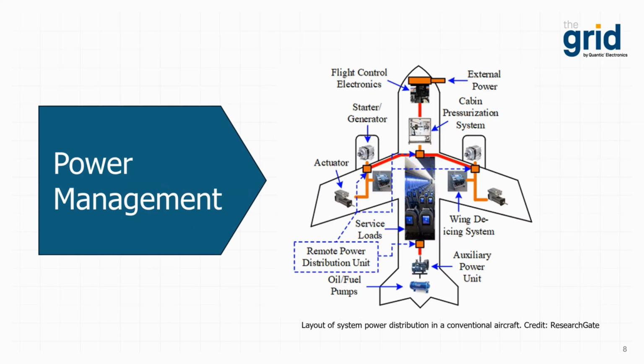Capacitors help maintain stable power supply voltage by decoupling and filtering out high-frequency noise. This is crucial for sensitive avionics equipment. Capacitors store energy to help critical electrical systems continue to have power during brief power interruption events, typically providing power holdup times of at least 50 milliseconds, as defined by standards such as MIL-STD-704 and DO-160. They provide energy when needed, which is important for systems that require uninterrupted power. Capacitors also assist in voltage regulation, helping to maintain consistent power levels across avionics systems.